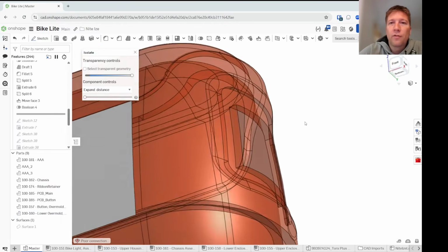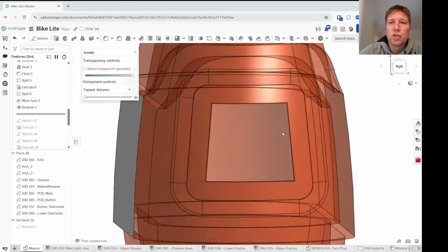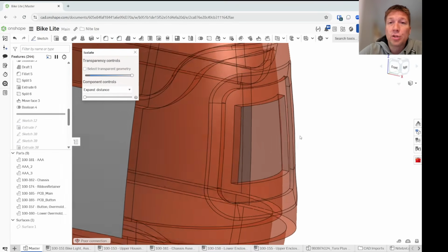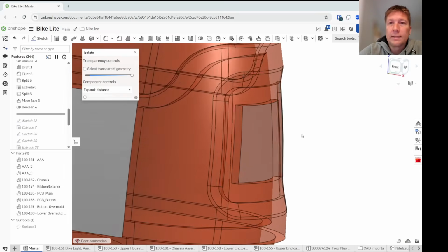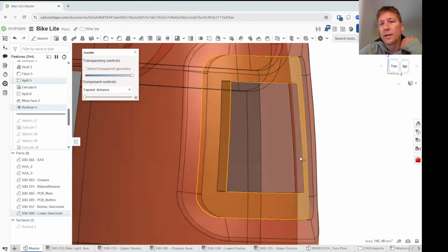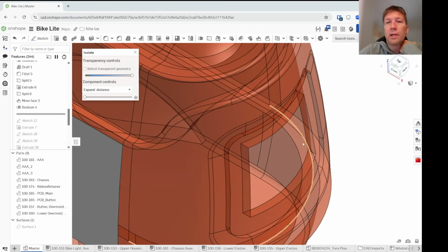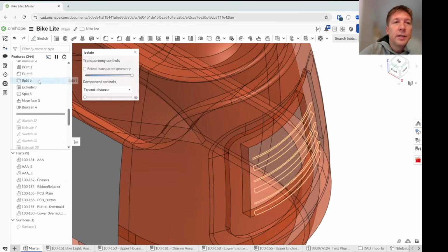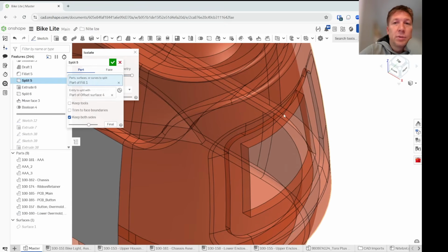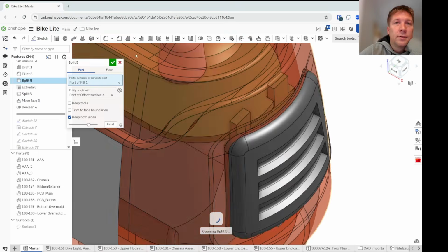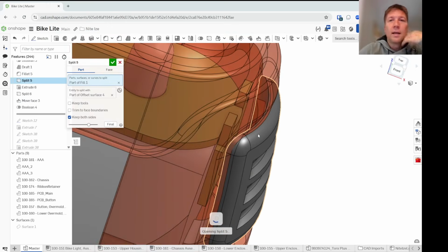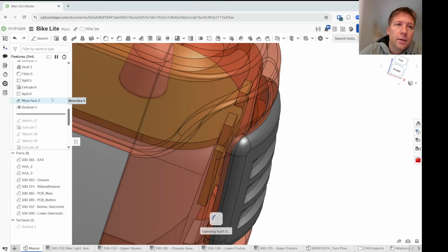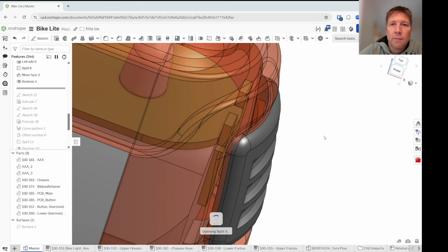There. So what I've created here is the sort of surface that the button sits in, because the rubber button is actually not full thickness. So in order to create this face right here, which is part of the rigid plastic overmold, I needed to first create that one surface, split the button in half, and then attach that body to the main enclosure. Hopefully that makes sense.